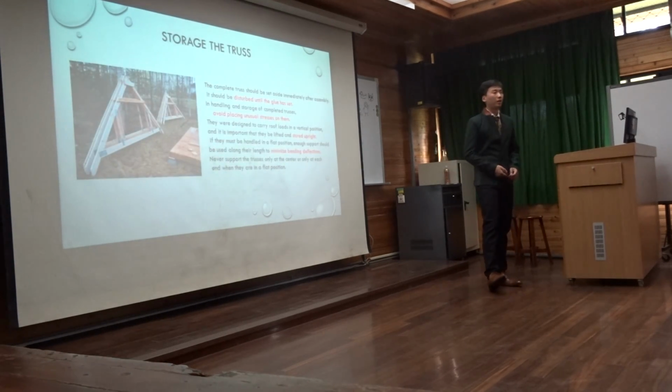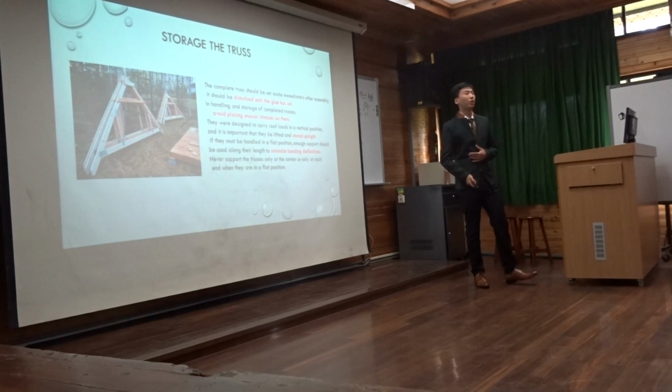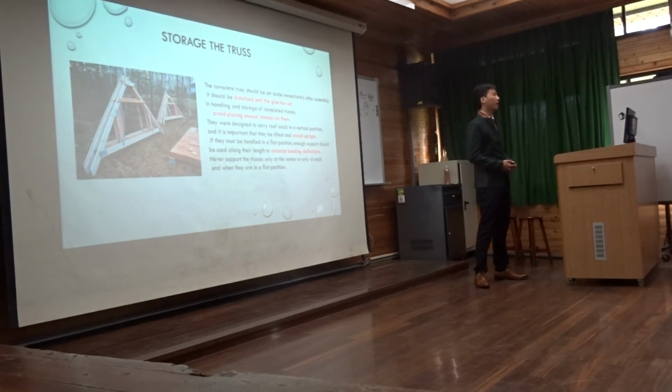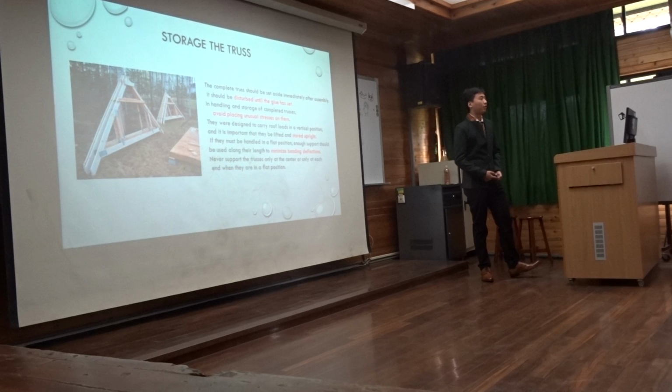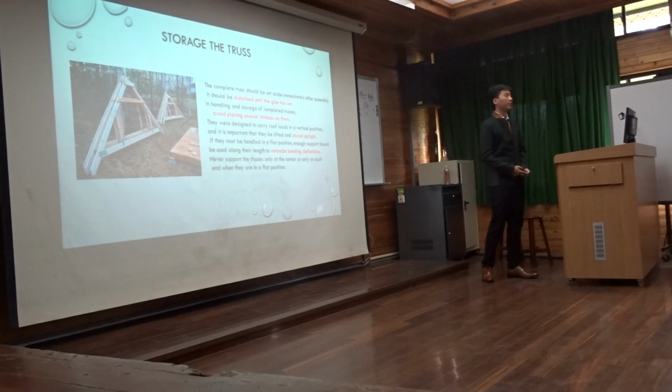After finishing a truss, we must know how to store it. The completed truss should be set aside immediately after assembly. It should not be disturbed until the glue has set. In handling and storage of completed trusses, avoid facing them to unusual stresses.